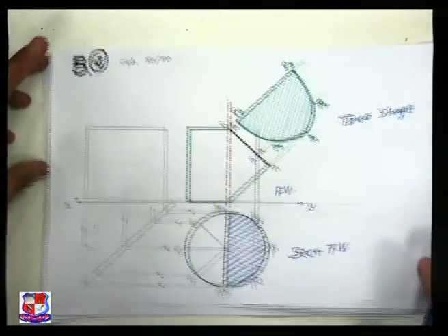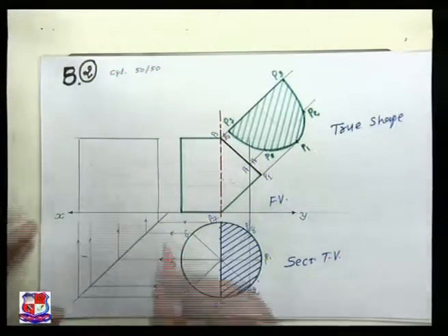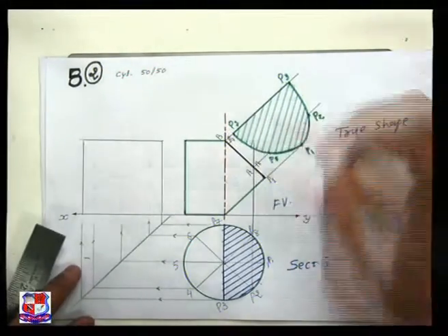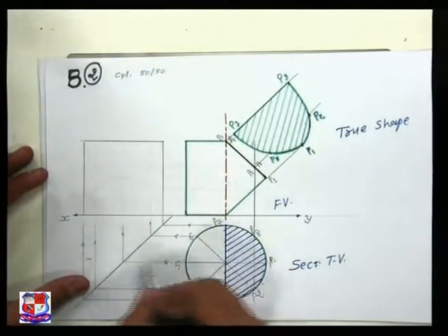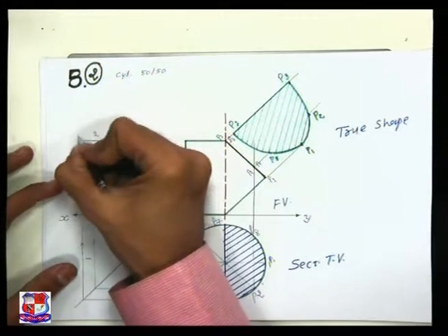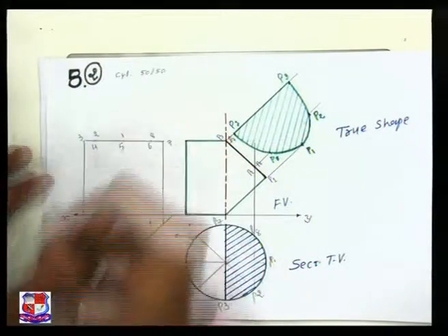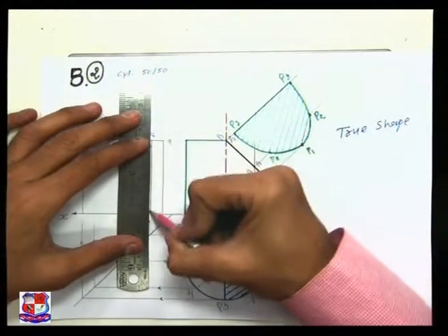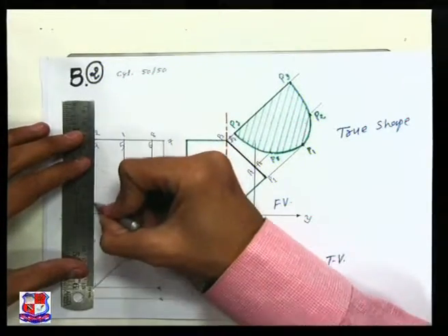Now the next step is to draw the side view of this cylinder. So for that we have drawn this side view. Now in this side view, identify the position of this cut portion. So for that, let me name the generators over here. Here generator 1 is at the middle, 2 is over here, so here is generator 2, 3, 4, 5, 6, 7 and 8. These are the imaginary generators drawn to the outside periphery of this cylinder like this.